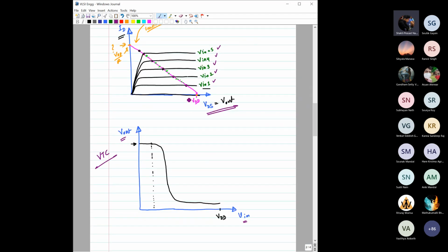So from that, you know that, right? Until and unless we reach this VTHN, the threshold voltage of this NMOS, the current would be 0, and the output voltage would be constant at VDD. VDD only. Okay, so till VTN. After that, what will happen?